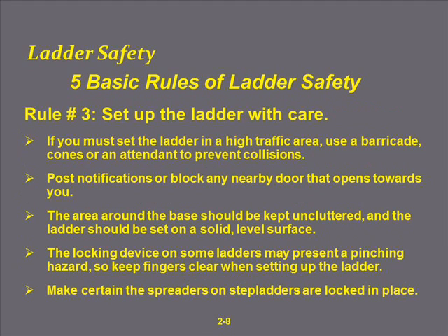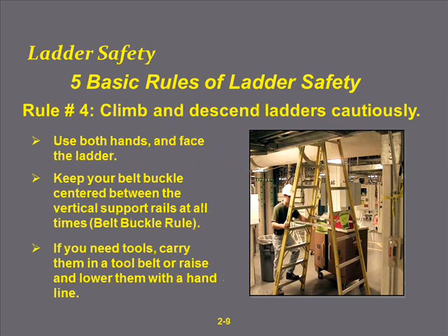Rule number 3, set up your ladder with care. If you must set the ladder in a high traffic area, use a barricade, cones, or an attendant to prevent collisions. Post notifications or block any nearby door that opens towards you. The area surrounding the base should be kept uncluttered, and the ladder should be set on solid, level surfaces. The locking device on some ladders may present a pinching hazard, so keep fingers clear when setting up the ladder. Make certain the spreaders on step ladders are locked and in place.